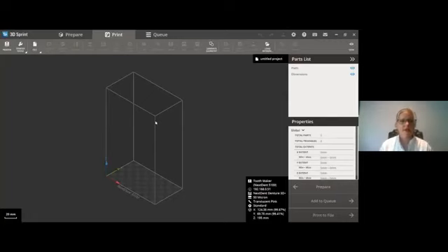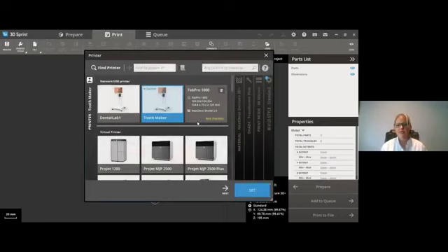Awesome. So I'm going to go ahead and cover stacking now. All of our favorite. Okay, so the first thing that you're going to do, again, if you want to do the stacking with peach or with gray, make sure that you do that material update when it prompts you, when you connect to your printer. I've already done mine, so it's not going to prompt me. And then you'll have to restart your 3D Sprint for any of that to take effect.